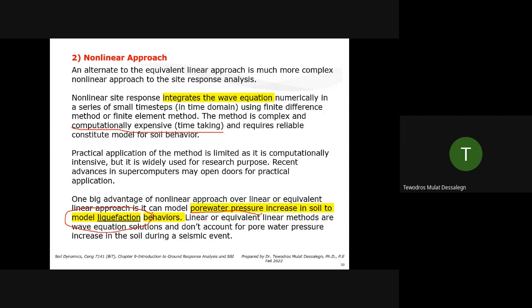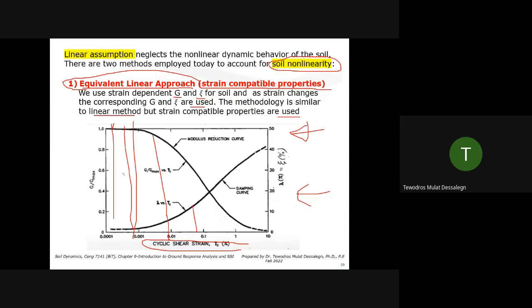But they use constitutive models for that. So, two approaches to account for nonlinearity of soil. The equivalent linear approach is much faster. The speed is helpful, especially if you're doing SSI, if you are modeling the entire structure above ground and so much soil underneath, you can do it quickly. It would be too difficult for FLAC and Plaxis to do that.